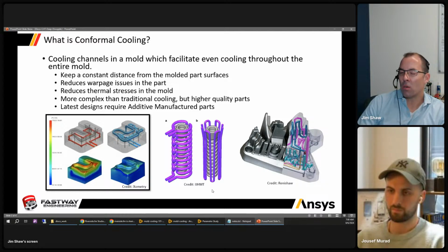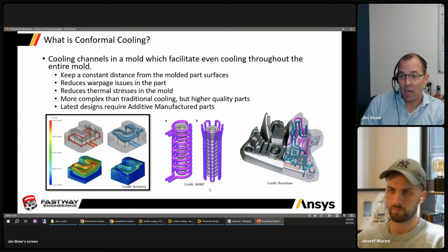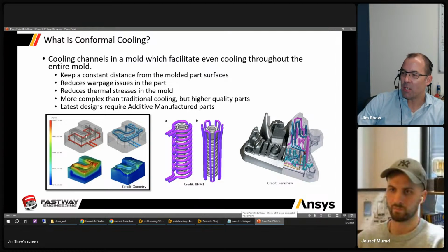So what are the other ways we might optimize? Here on the left-hand side, I'm optimizing for mold temperature. The other things I might be optimizing for are minimizing the flow rate, so I don't have to have as massive a pump, minimizing the pressure drop, right? We have a fluids problem here because somewhere there is going to be a pump and a working fluid, and that needs to go through this circuit. So I've got some physics in addition to the geometry. I've got some physics I get to optimize.